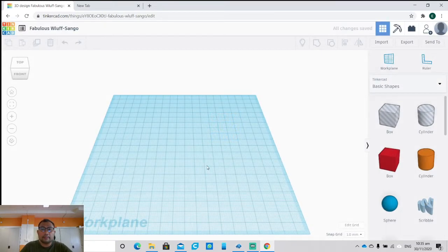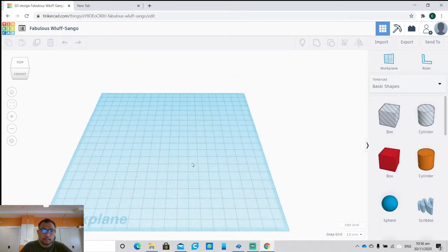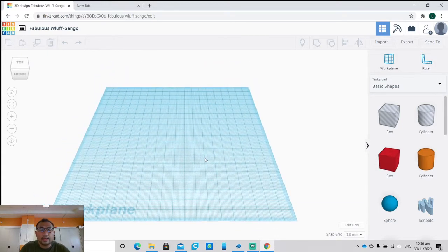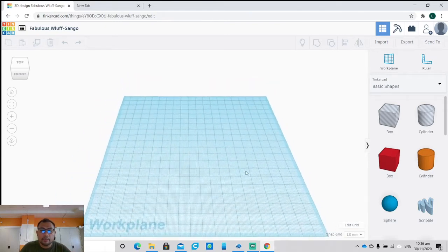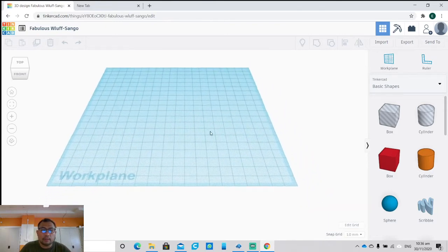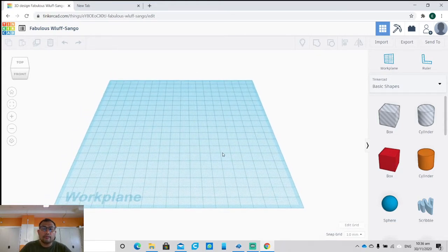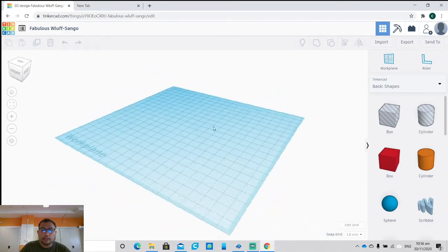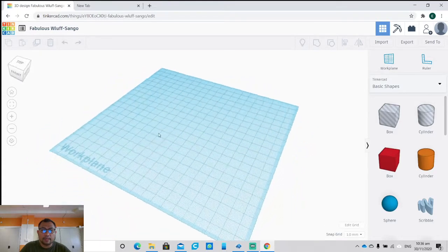So this is the platform that you can see. On your mouse, you can press the center button. It will shift the work plane, keeping in mind that it's locking on to the perspective that you are at, but you are just moving the work plane according to your mouse motion by holding on the middle scroll wheel button. Now if you wish to pan your perspective, hold the left button and you can shift your work plane to any perspective that you like.